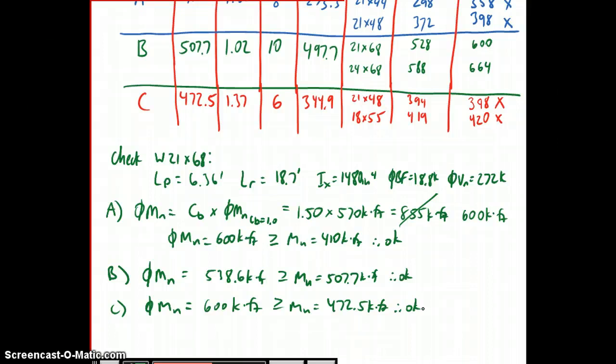works for flexure in our beam is to account for self-weight. Now for a simply supported beam with a uniform distributed load, we know the equation for max moment is wL squared over 8. We're going to use that, however we have to be cognizant that that's going to be a little conservative.